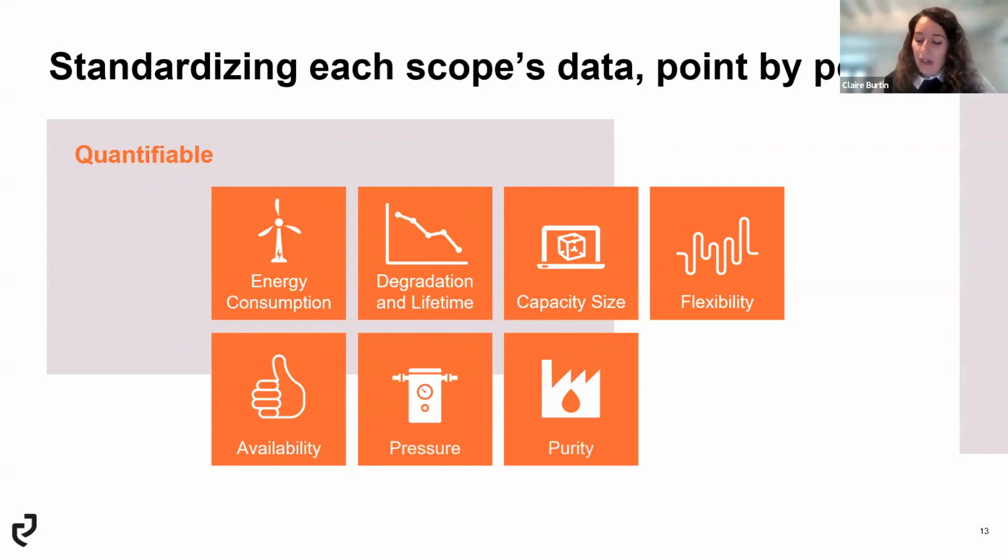The energy consumption of the electrolyzer is going to be varying depending on the load of the electrolyzer. So if for your project, for example, you intend to use all the electrolyzers at 60% of their load because for some reason, in terms of energy supply, it's better for you, you must ask your supplier to provide you with the energy consumption for their system at 60% load.